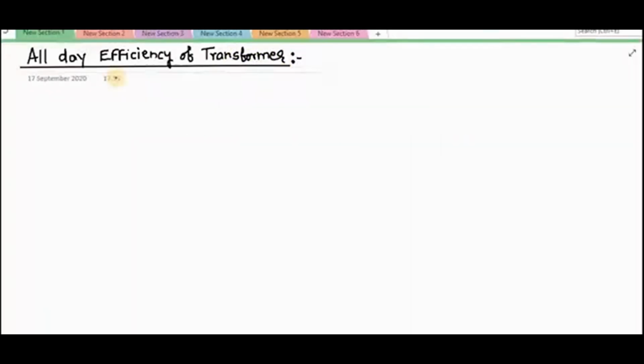So, students, transformers are of two types: distribution transformer and power transformer. The power transformers are normally used for the transmission of power, right? Those are used in the substations, receiving end substation and sending end substation, as well as secondary substations. But distribution transformer means the transformer supplying our lighting and domestic load or general electrical network. Those transformers are called distribution transformers.